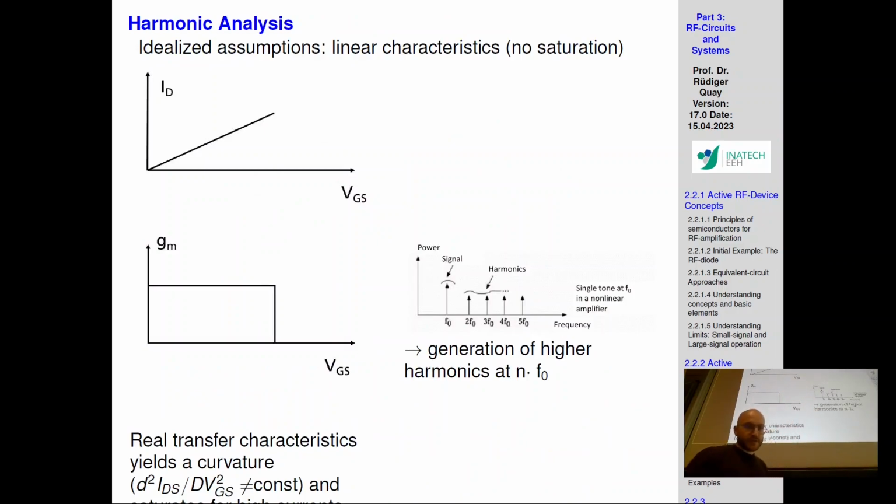Usually you would expect the device to be linear. You know, your device is great, you have a constant gain, and the gain just dies at some point because your device will die. So your device is always the same. I'm giving it 100 dBm, it gives me 120 dBm, I'm giving it 80 dBm, it gives me 100 dBm, I give it 60 dBm, it gives me 80 dBm, my device is at 20 dB gain, solid, all the way through. But that is obviously not the case.